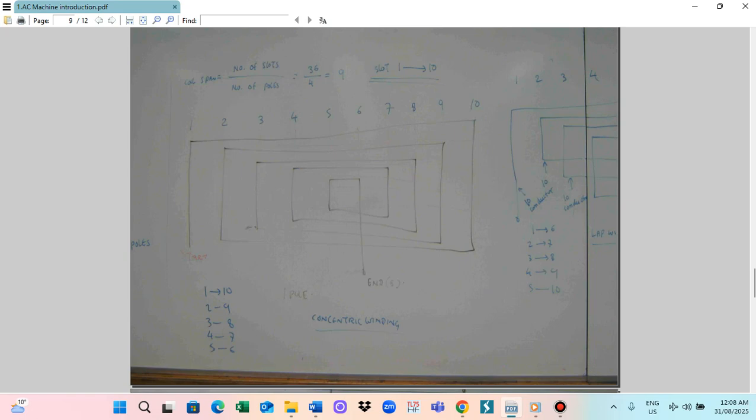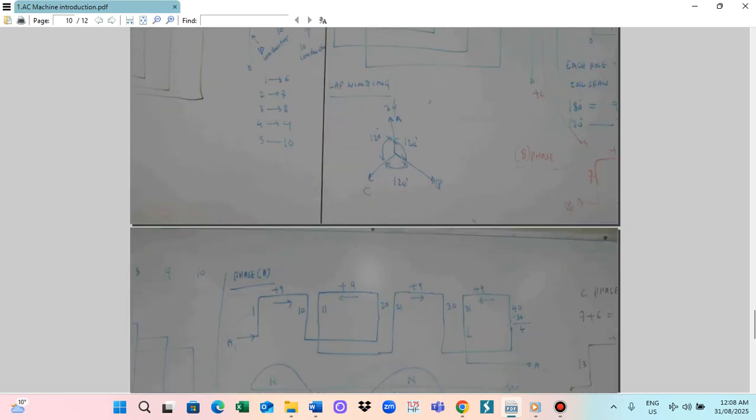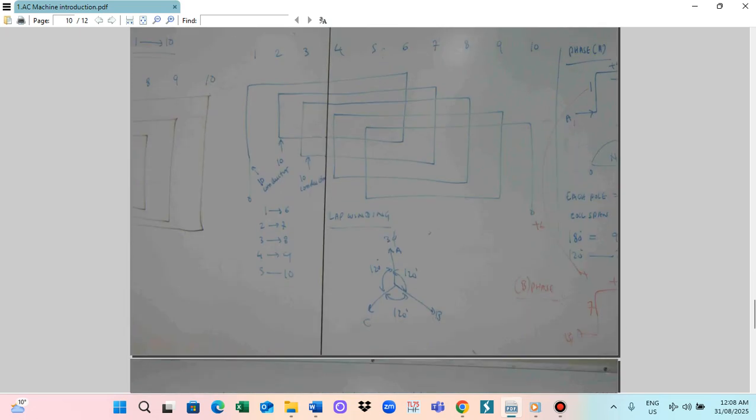On the timber you put the winding former. The winding must not be too tight or too loose. If too loose, the windings come out to the cover, and the motor shaft can cut the winding. If too tight, you cannot properly put the winding in. So this is also important. Motor winding requires very skillful work. This is how we make either the concentric or the lap winding.